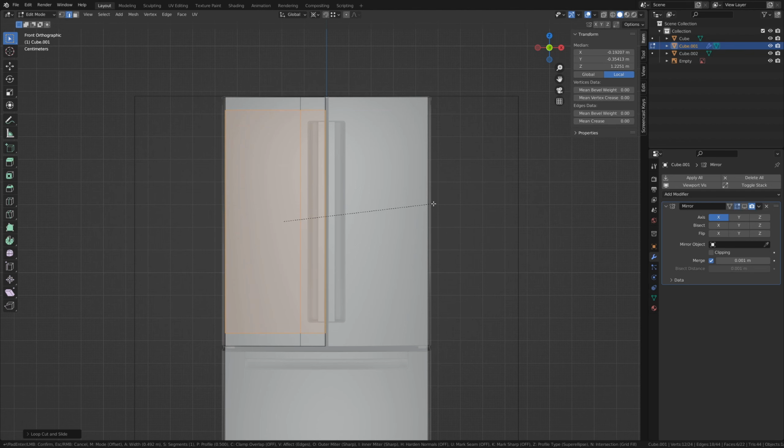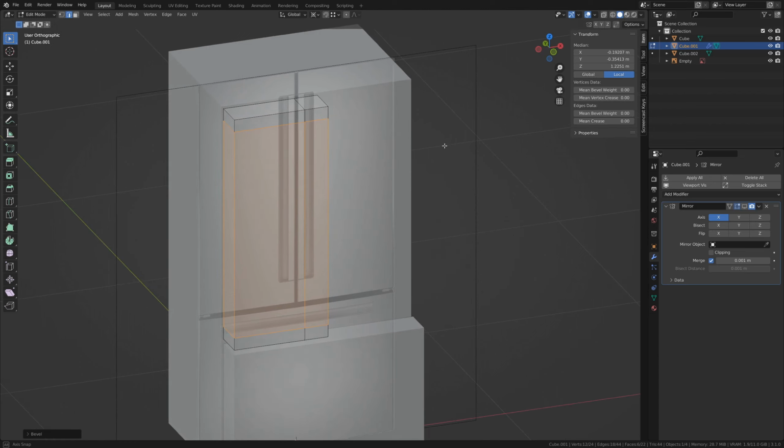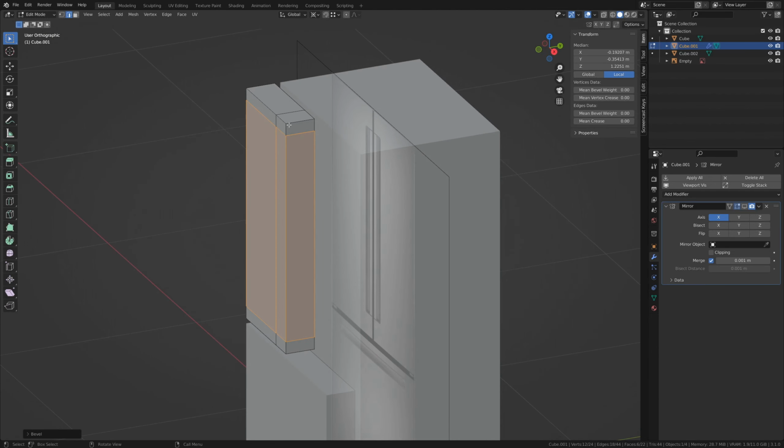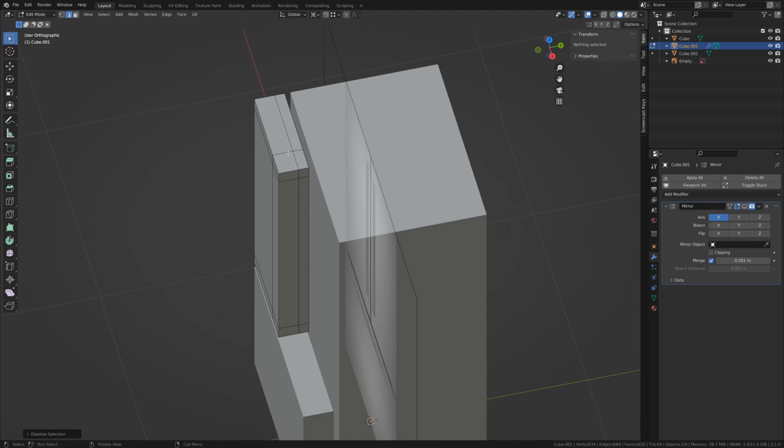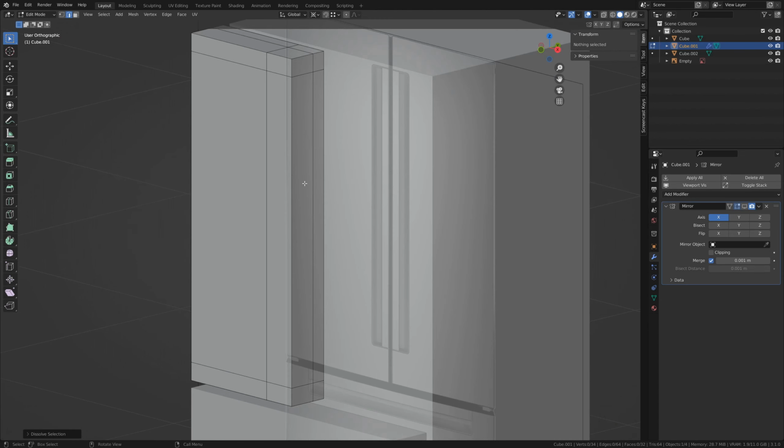About there. It needs to encompass the handle, and it's going to give it some breathing space because we need control rings so that all this geometry that's about to be created in here won't spider all over the rest of the mesh. So put another one here. Actually, let's do two and delete this forward one. That's just so we have some even spacing. It doesn't really matter if you do 2 and delete 1 or just put 1 and slide it where you want it.